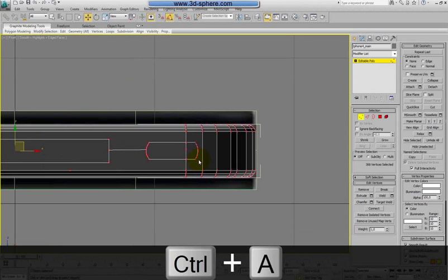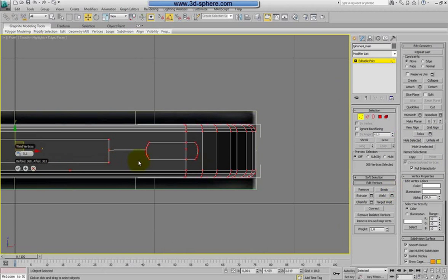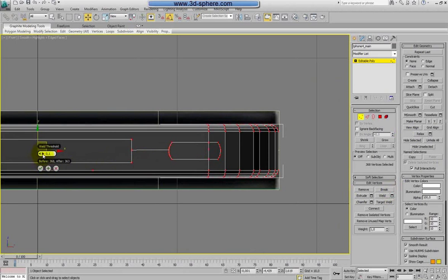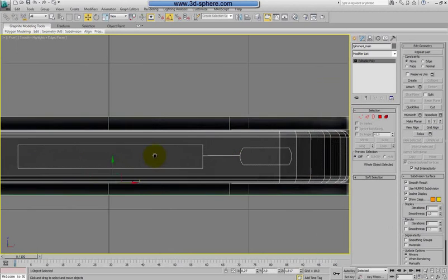Now I will select all vertex and go to weld, and let's adjust this, maybe not so big. We can weld something which we don't want. Yeah, so you see before we have this number and now we lose 5 of them. So there was some very near each other and we just delete them like this.